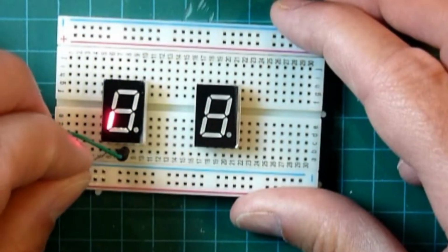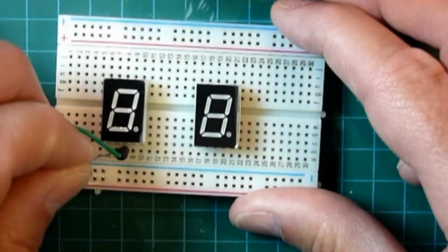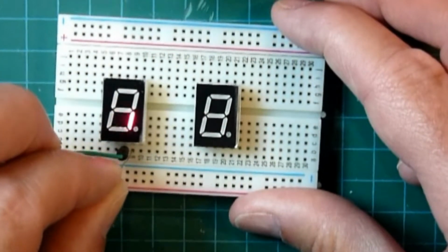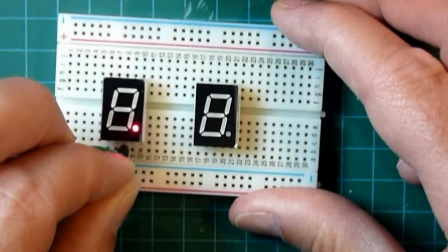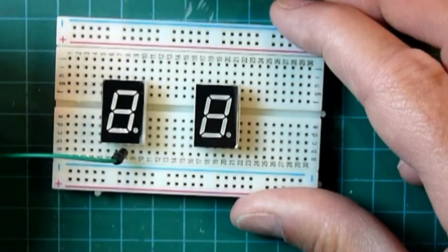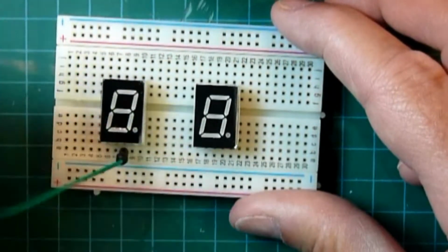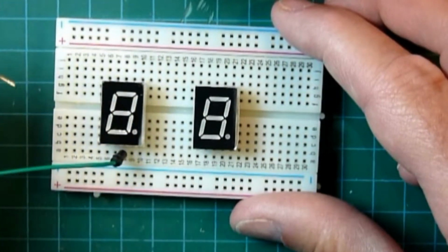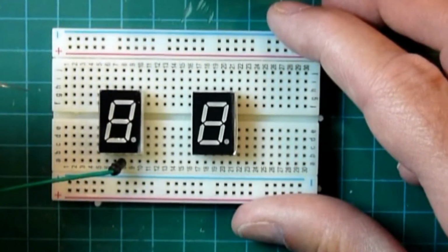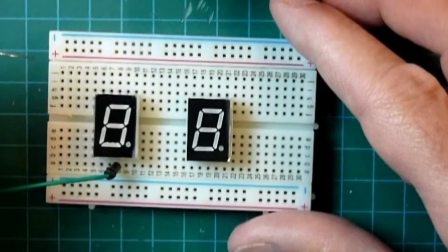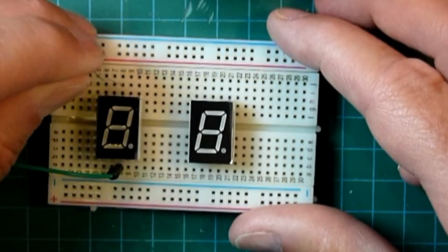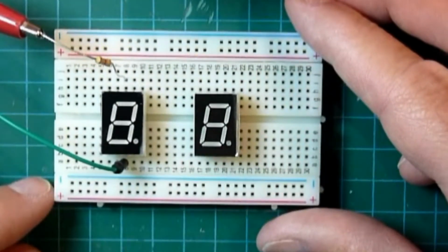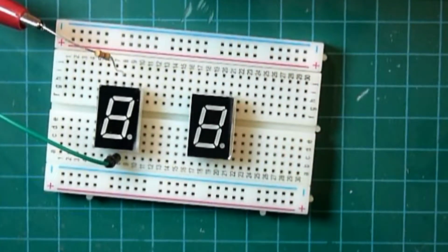If you're not sure, this is one way you can figure it out as well, if the spec isn't clear to you. So there you go. You see the different segments lighting up. Here I'm using a small resistor in the few hundred ohms range. I'll show you how to determine that in a little while. Now let's put a voltmeter across this and see what kind of voltage drop we get. According to the spec, it's approximately 2 volts.